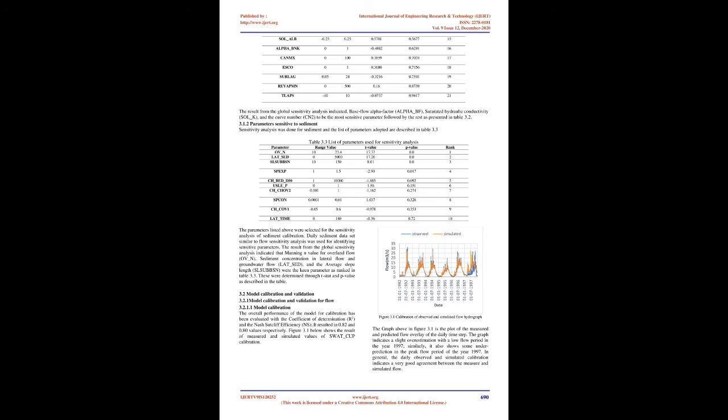If ENS is negative, predictions are very poor, and the average value of output is a better estimate than the model prediction [6]. This coefficient is calculated by equation 2.2, where the first variable is the observed, measured, stream flow on day i, m3/s, and the second is the simulated stream flow on day i, m3/s.